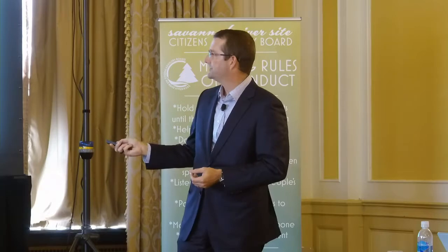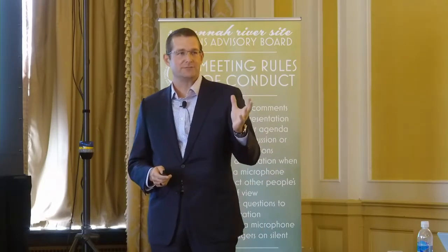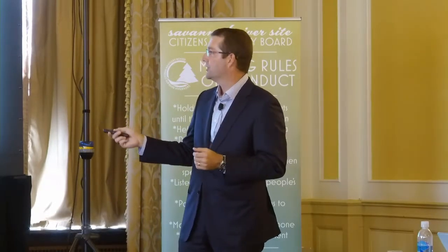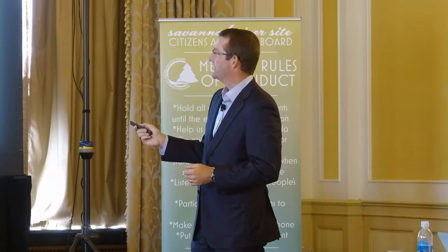We've got 2 blenders, which means we can run them out of phase. So while one blender is actively in its blend cycle, the other blender can either be receiving material from the weigh hopper or it can be discharging to our main process building. Exiting the air blenders, we go over, and this is shown as a very short line on this chart, but it's quite a physical difference in separation. But we go over to our main process building where we have the premix feed bin. And the premix feed bin is where we transition from batch operation to continuous operation.